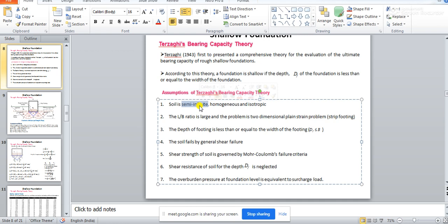If there is a three-dimensional material, and most things are three-dimensional in nature, and the elastic constants in all directions remain the same, that means modulus of elasticity, Young's modulus, Poisson's ratio remain the same in all directions, in such a case the material will be called an isotropic material.